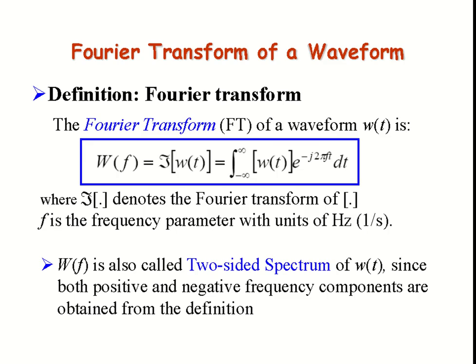So basically this lecture is a review of the concepts which you have learned in signals and systems about the Fourier transform. So we know that if we have a signal in time domain, and you multiply it with exponential power minus j 2 pi f t, and integrate from minus infinity to infinity, that will give you the Fourier transform of that signal. So basically the Fourier transform pair can be written like this. Or we can also write this in omega form. This is angular frequency, this is the simple linear frequency. So this is called the Fourier transform pair for a signal.